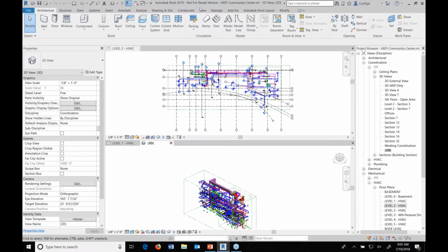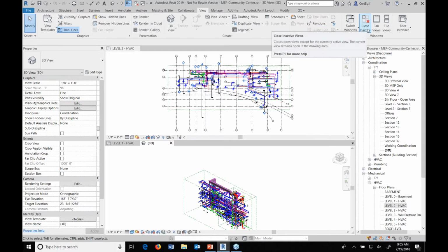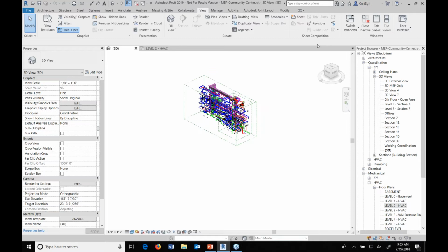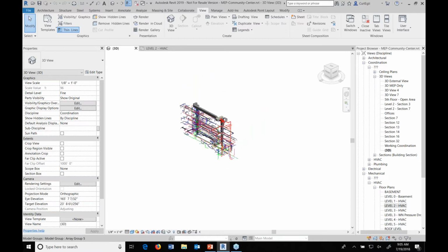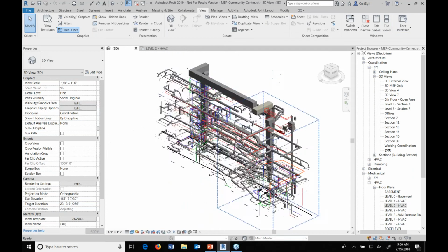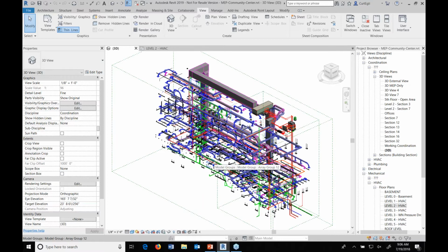On the View tab, they've added in this, which is to close inactive. So there's 2 new buttons out here, close inactive. You see how it closed down the 1 tab and still left these open. So you don't have to close down everything but one, which can be very helpful there too. If you want, you can use this tab views here. It's also TW. TW will combine them back together again so that the windows will get tabbed back into a single tab there. Okay.